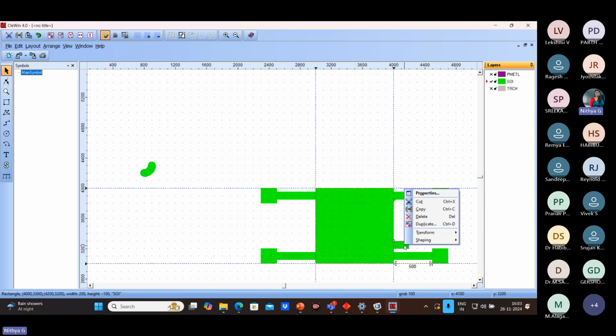It takes little time because we have to create the trench at every point, these fillets, creation of the trench and the dimension of 3 micrometer gap. All those points need care, because otherwise, even if the device simulation is correct, if the mask file is not created in the right format, then there is a high chance of the device failure. Maybe again it will be at the cost of so much money and so much effort from everyone. So please make sure you follow these minimum criteria, minimum geometry rules, minimum gap that has to be considered when you create the geometry.